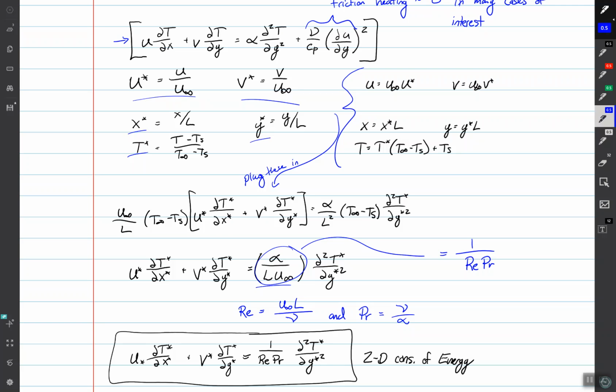The Reynolds number and Prandtl number are what's dictating the conservation of energy aspects. And for convection, the Nusselt number. So those are going to be our three groupings of variables that we are really going to care about when we're talking about the physics of convection. And we'll dive more into that next time.